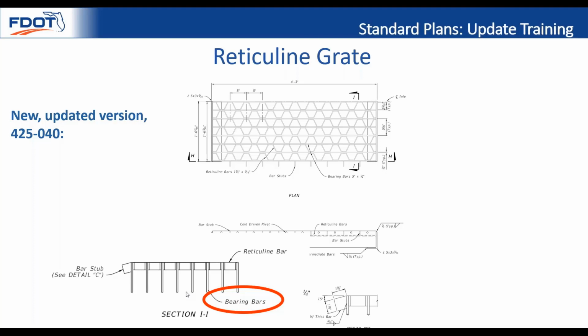And now there's only one grade, whereas we had some before where producers would tell folks there's an option for either basically the pedestrian grade, which is what they tabbed what we had shown in the standard plans, or if you needed an H20, then there was a grade similar to this one. So end result, only one grade for those indexes, and that is what should be installed in the field.